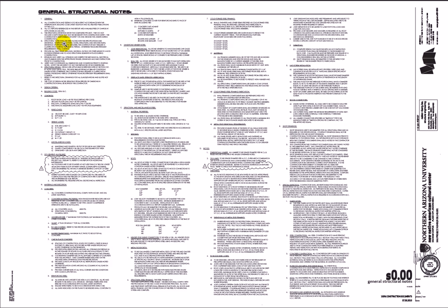So I'm going to go back to the beginning, the general structural notes, and the general structural notes really give the detail about this type of building. There are specifications that will tell exactly how to build each part. However, the structural notes are different than most other trades where the specs take precedence. In structural drawings, typically it's the structural notes that take precedence over the specification.